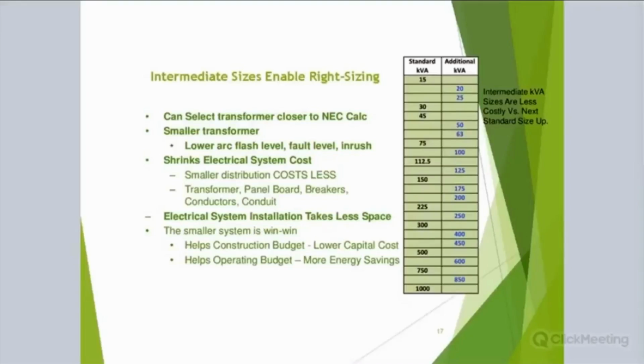If I have a 150 kVA transformer and it is, let's go on the high side, typically loaded to 15%, that would mean that the load it'll actually see is 20 kVA, 22.5 kVA.